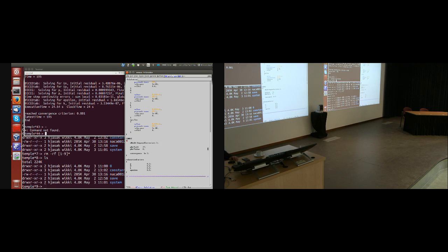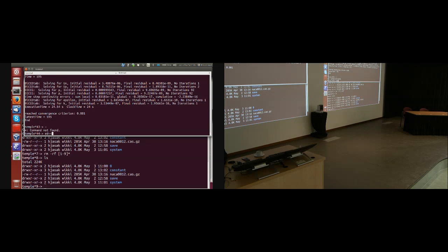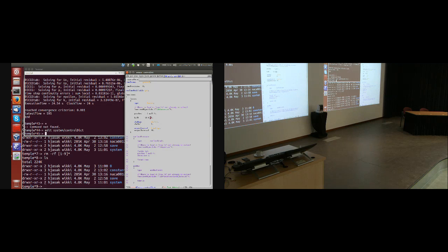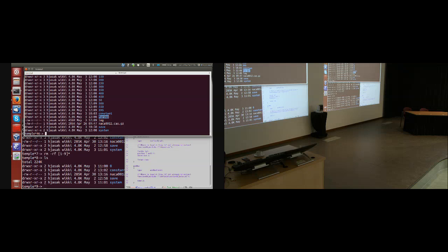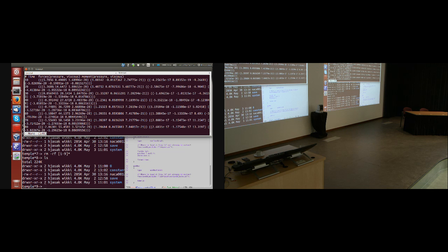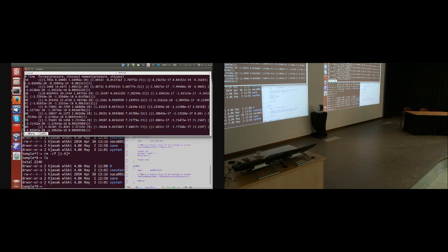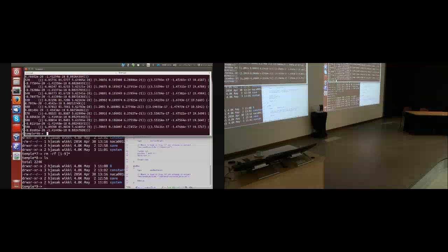Okay? You remember how we switched on the function object for the force in the control dictionary. Okay? That produced the output in forces in the 0 directory. Okay? And here it will say time, 10, 20, 30, 40, forces, pressure force, viscous force, moment, pressure moment, viscous moment around the point 0, 0, 0, and you can follow what these forces are doing.